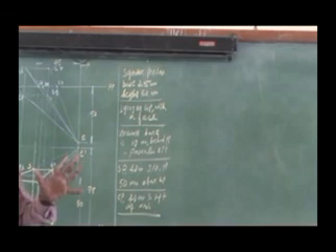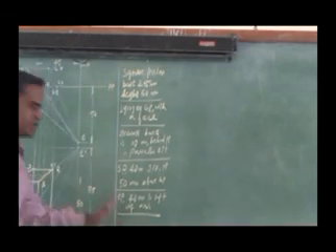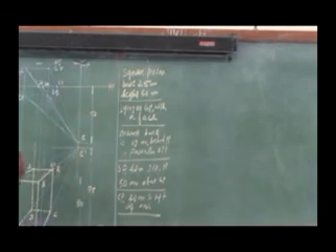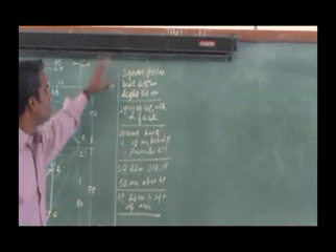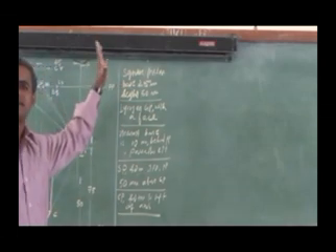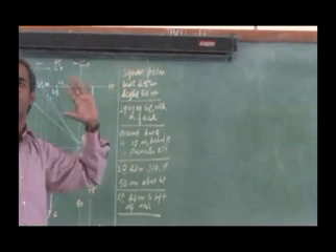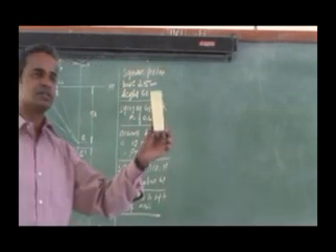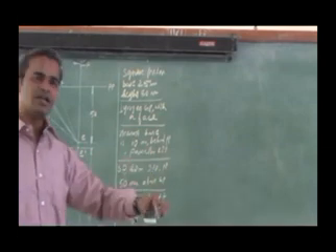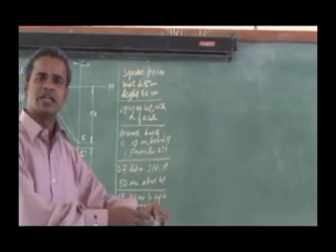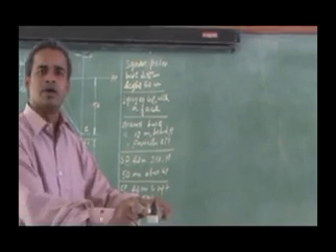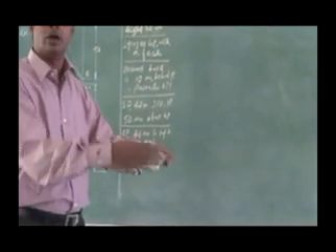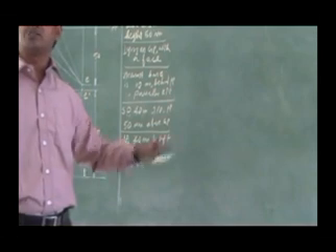Similar to the first problem, right? The center plane is to the left, similar to the very first problem. The station point in front and above distances are given directly. What is the difference here? It is this solid's orientation. So far the solid was kept vertically like this. Now the solid is like this, so this is going to be the nearest base. It is lying on its face. The nearest base is 10 mm behind the picture plane, and it is parallel to the picture plane. That is the difference.